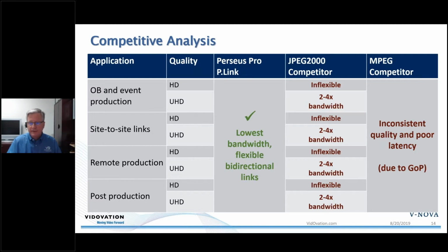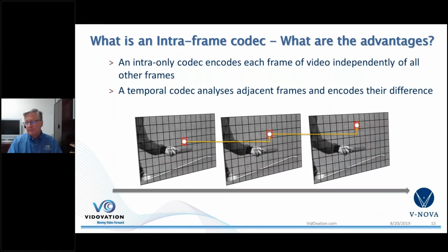coming into the field. And because, unlike a temporal codec like MPEG or like H.264 or HEVC, we're only compressing in one frame, not across frames, we don't have a group of frames or a group of pictures like these other standards. Temporal or motion distortions or anomalies are minimized. I'm sure many of you know the difference between intra-frame and inter-frame. But if you have motion here, here's a little diagram.